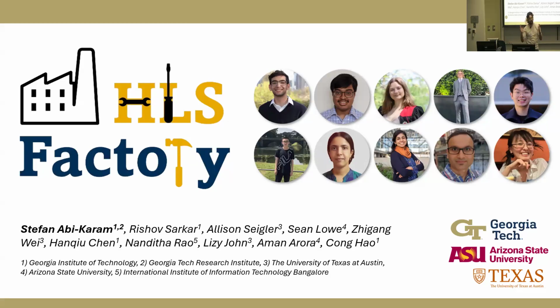So we recently published a work where we use LightningSim to explore different sizes of FIFOs within your design. And actually LightningSim lets you change the size and recalculate the latency without having to resynthesize the design. That's the only thing that you can change and quickly resimulate and get new numbers for. Everything else you have to resynthesize.